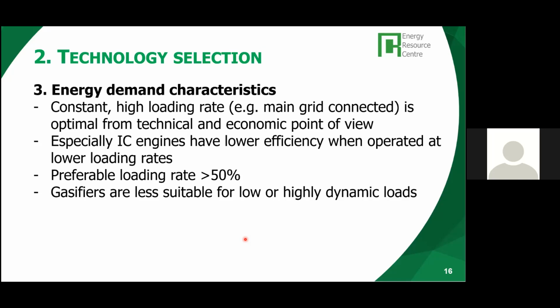Especially when you look at internal combustion engines, particularly gas engines, but also diesel engines running, for example, on vegetable oils. You will see that when you operate them at a lower loading rate, you will have lower efficiency, and this is particularly true for spark plug engines.